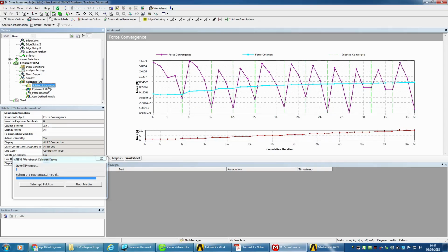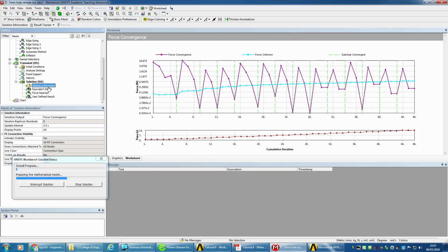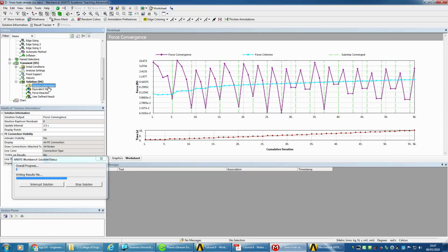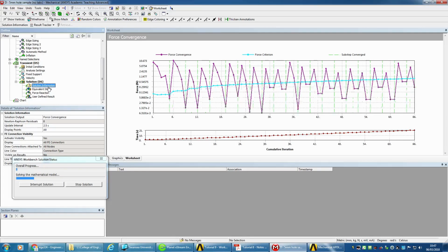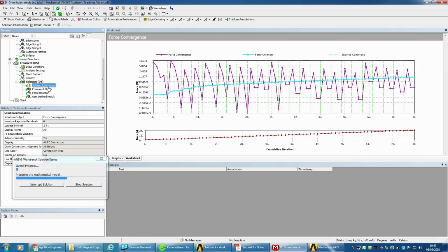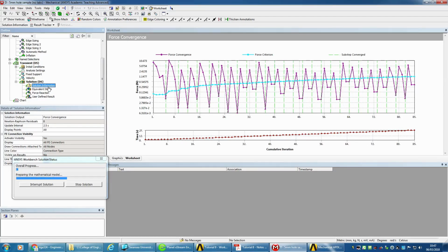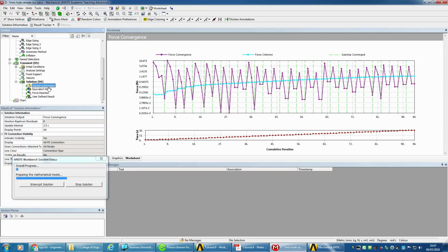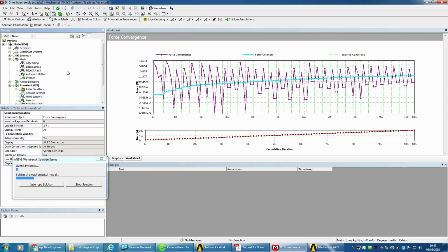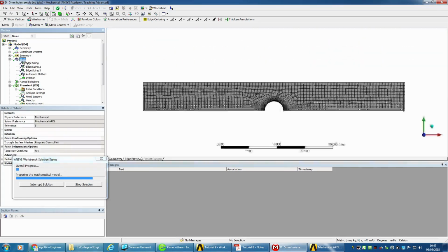So this should go pretty quickly because it fails pretty quickly. I'm just trying to keep everything constant except the geometry now and the mesh, obviously. And this one we've introduced a 5mm hole. Where before we had a 2mm hole here, now we've got a 5mm hole. Then there was, last year anyway, an 8mm hole sample which failed almost immediately as soon as you pulled it.